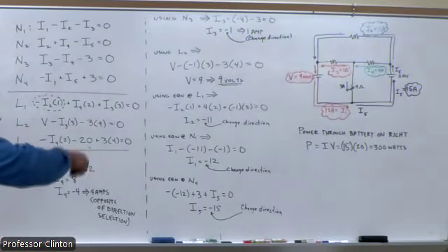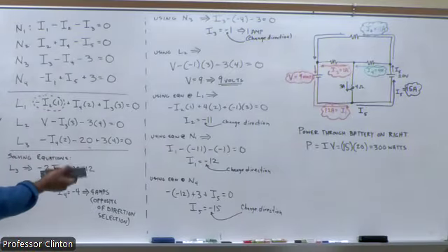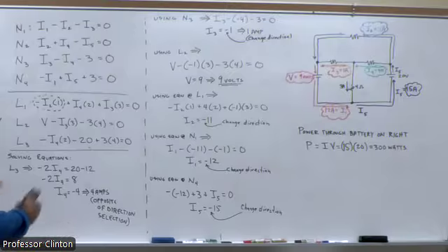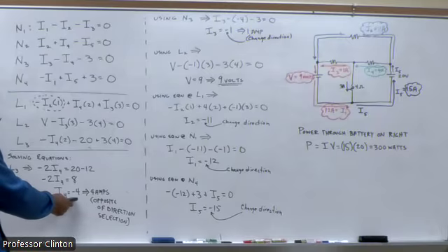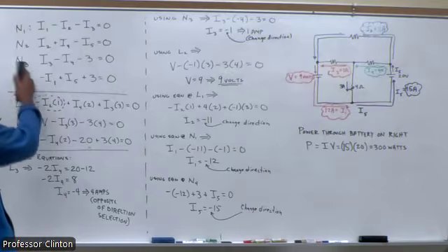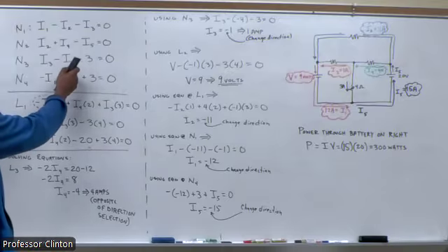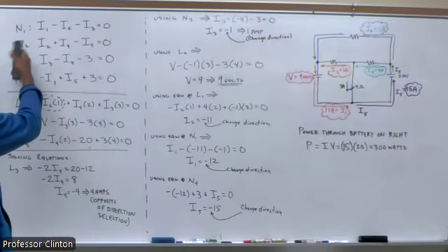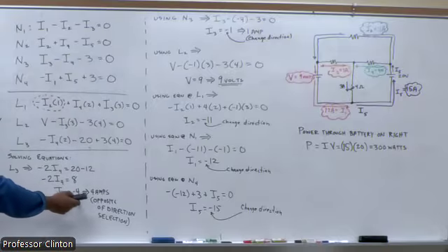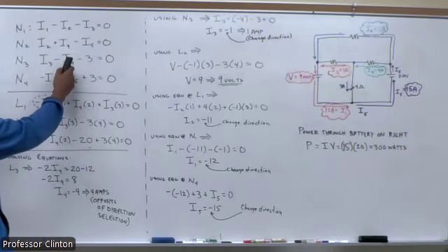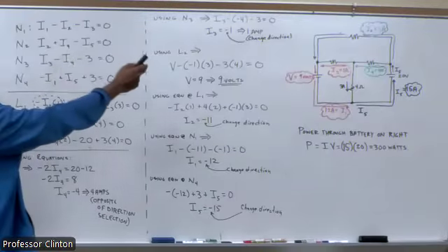You'll see, again, I'm looking for an equation such that I either have one unknown or I can substitute. So in this case, since I have what I4 is, I realize that I can go into this equation that comes from the node equation or the sum of the currents. And I just simply plugged in here for I4, solving it.